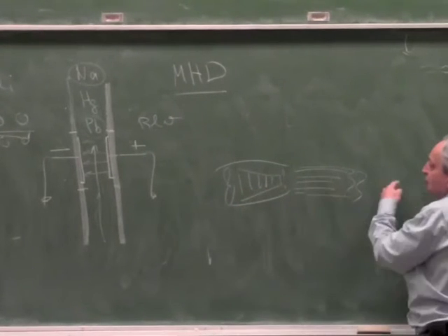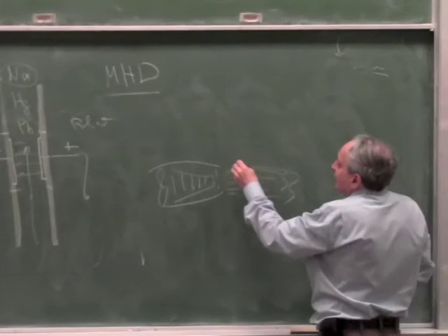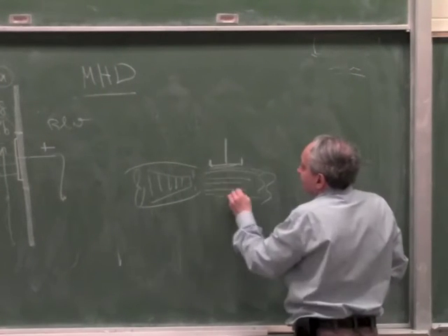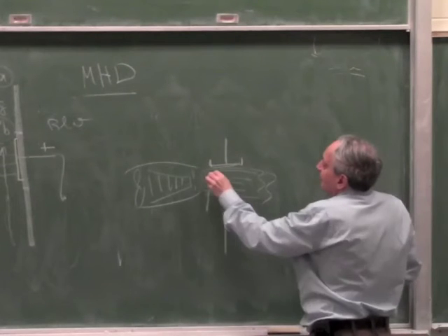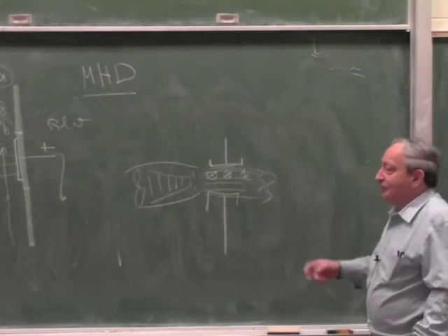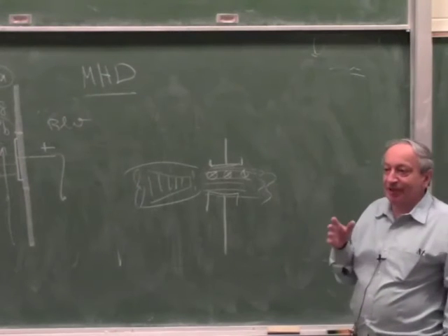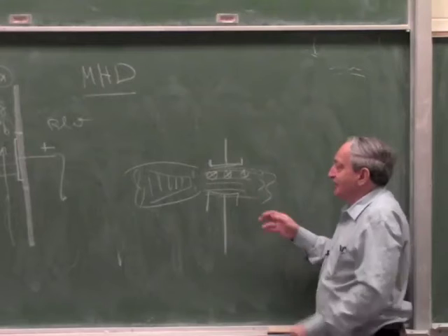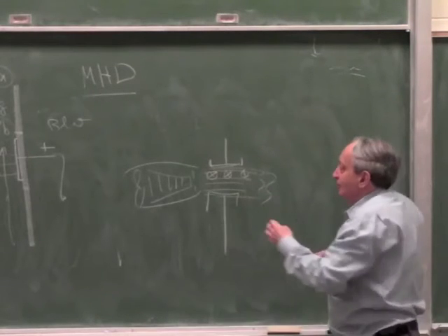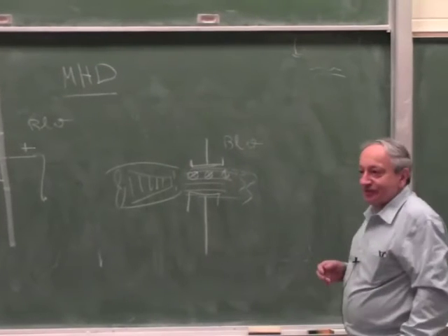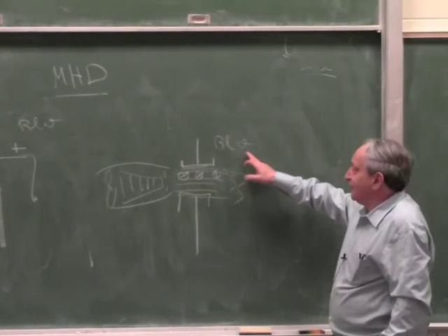Now in this huge flame the jet engine shoots back, we put two big electrodes, like this, and we put a magnetic field at right angles. Now this conducts because that's plasma. Again, plasma meaning ionized gas. But the advantage of this is it moves very fast. So a voltage will be generated here, BLV, okay? But V is very high.